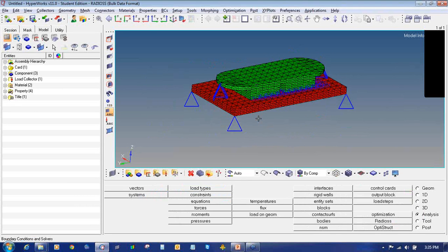First we will create the EIGRL and EIGC cards. In this step, a modal method is used to solve the complex eigenvalue problem, which is more computationally efficient compared to extracting the complex modes directly. With this approach, first, real modes are calculated via a normal modes analysis. Then a complex eigenvalue problem is formed on the projected subspace spanned by the real modes and thus much smaller than the real space. In this case, both EIGRL and EIGC cards need to be defined.